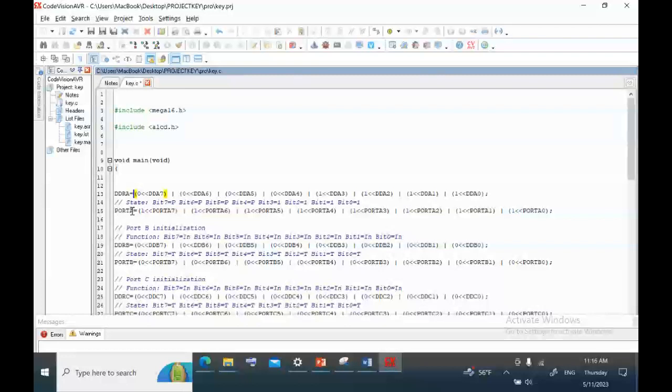You see that also port A, all of the bits initial value is equal 1. The input bits have pull-up resistor activated, you see that. And the other first bits, which are configured as output here, have initial value equal 1.